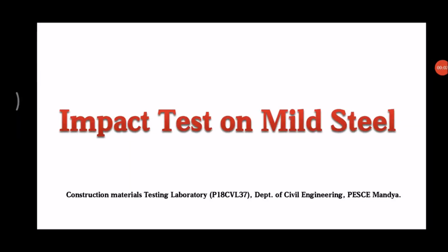In this session, let us conduct the experiment on impact test on mild steel. So what do you mean by impact load? The sudden load acting on any member is defined as impact load. The impact test determines the amount of energy absorbed by a material during fracture. This absorbed energy is a measure of a given material's toughness and acts as a tool to study temperature dependent